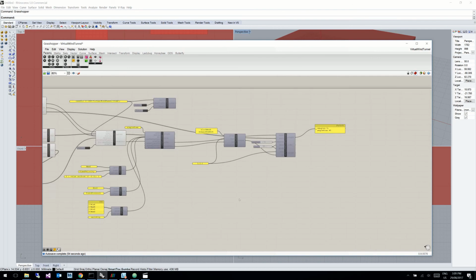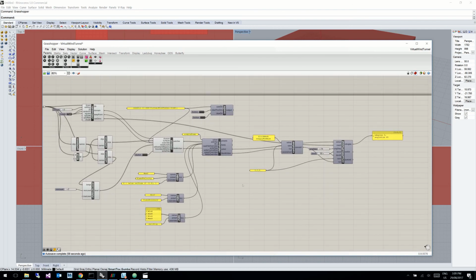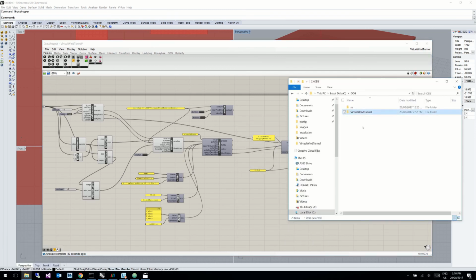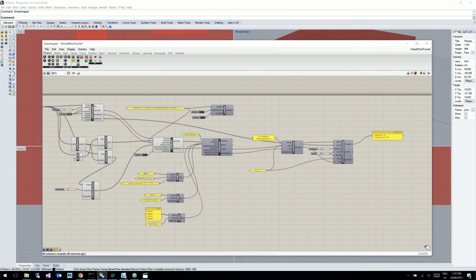So that's it, the case is all set up now. We're going to write the mesh files, write the solver files and boundary conditions to create a full case, which will work for SimpleFoam. We're going to run the meshing commands, blockMesh and snappyHexMesh, across 4 CPUs, and then we're going to solve for 8 wind directions at an angular step size of 45 degrees. These will all be run sequentially as we press a button. So let's delete our previous folder and see how it runs.